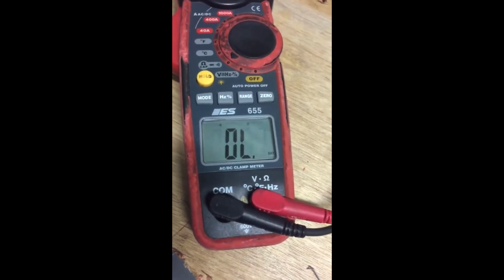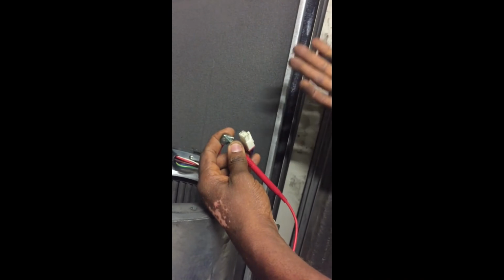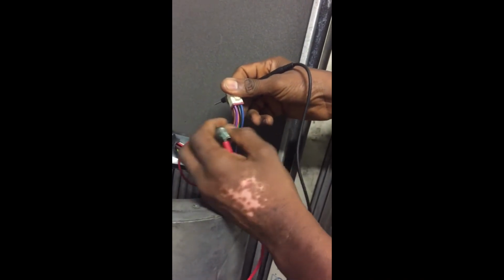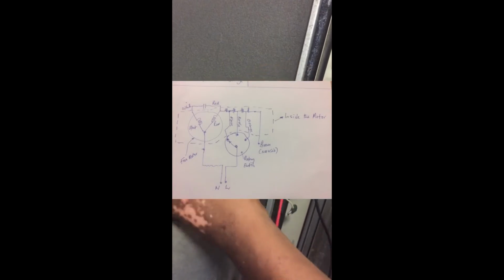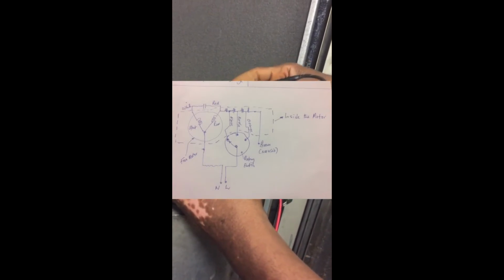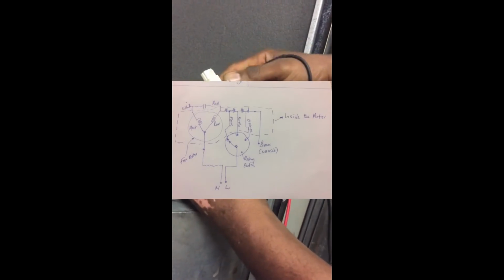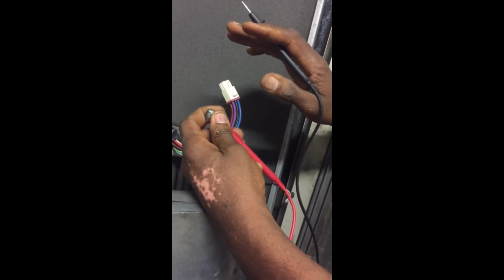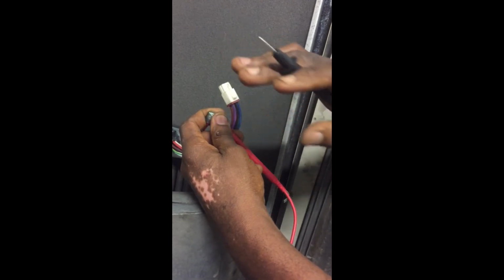So that clearly shows that internally all the wirings between power supply and the run terminal are in place for all the speeds. So power comes in through the black cable, which is at high speed, and goes to the run terminal. But the current is reduced because of the resistance that has been placed there. It's not the full speed.